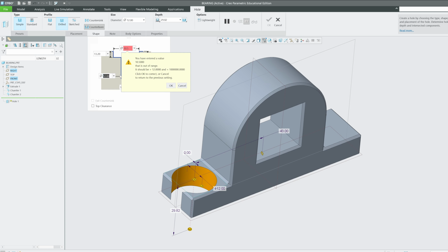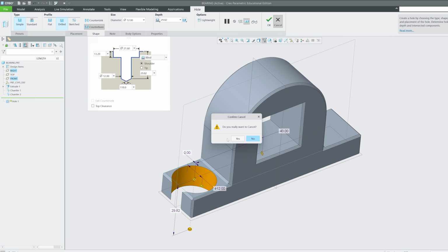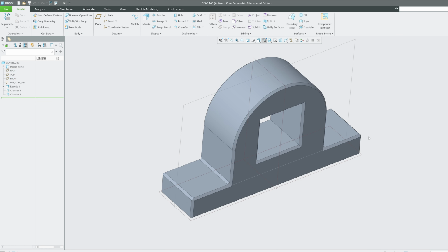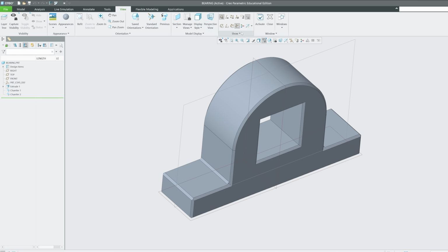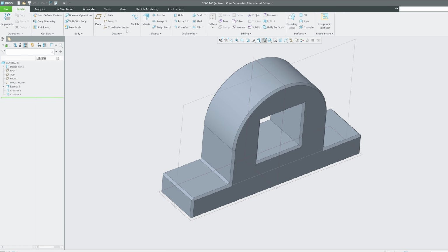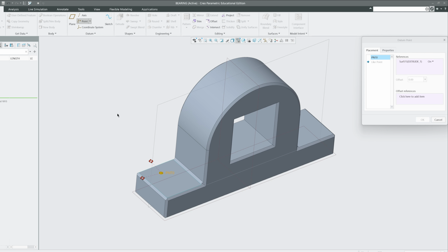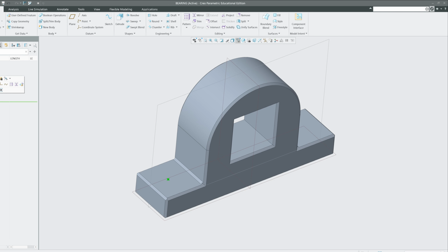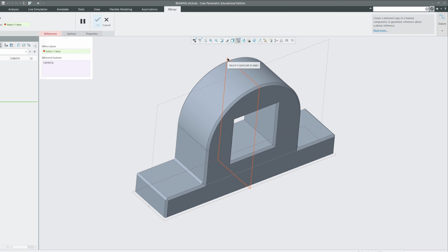Of course I'm gonna reduce this. Let's make it 6.1. Or maybe what I can do is use IFX, Intelligent Fastener Extension, instead of manually putting bolts. But for that, at least I need to have some kind of points. So let's add a point actually. Let's again take offset reference collector. I'm gonna make it 0, and let's make this distance 10. That's good enough. Now I'm gonna mirror this point to the other side.